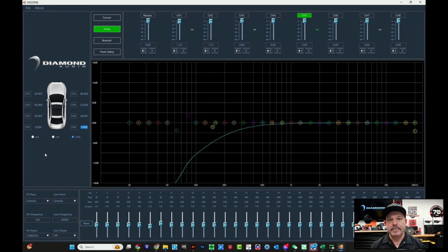So you may want to boost a little bit in your upper mid range. You want to add maybe a little bit more bass, and you can do that in a couple ways. You can do it like this is the EQ, and you can go in and adjust these frequencies, and you can add a little bit, cut a little bit, depending on what you're looking for. Or if you like it flat, or you don't want to do that much adjustment, maybe the customer has a head unit that has bass, treble or some other adjustments at the front, and you just want to give them something flat to start with, you can leave those alone and not adjust it at all.